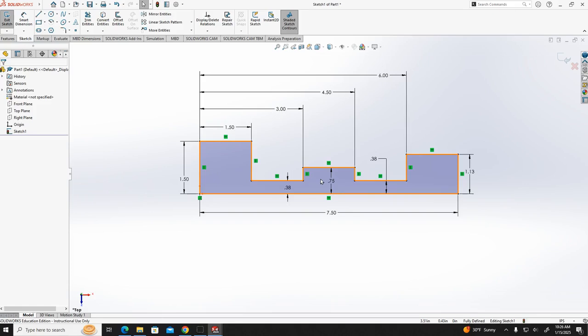I'm trying to figure out how you got all the dimensions. So click on Smart Dimension. Yeah, that's what I mean. Smart Dimension, and this line to this line. And then just drag it down, so that you just place it below the line. Then I'll fix the numbers to what they are. Click on 7.5. So check whether your number lock is on, and just press enter.